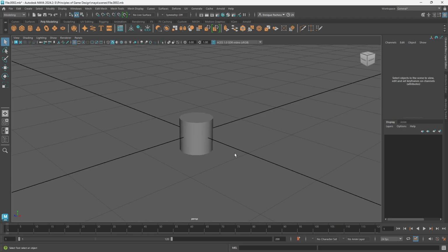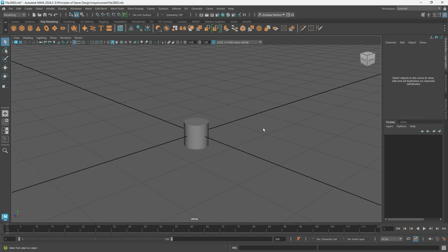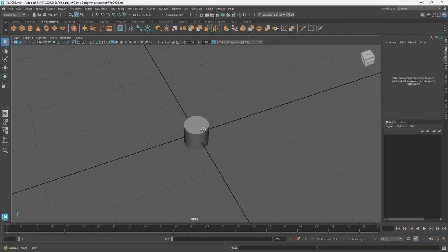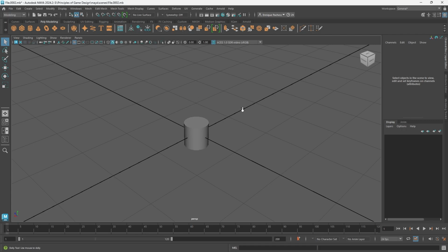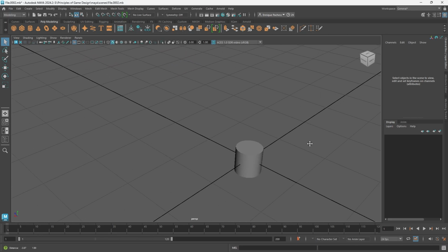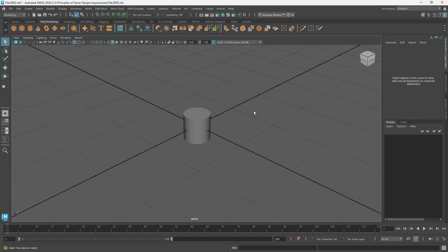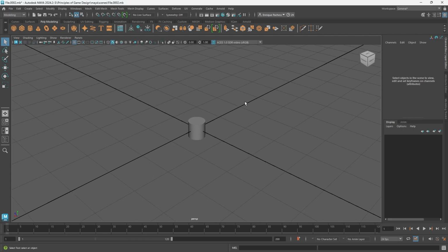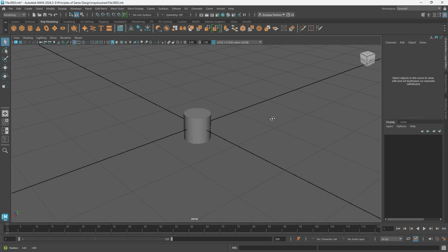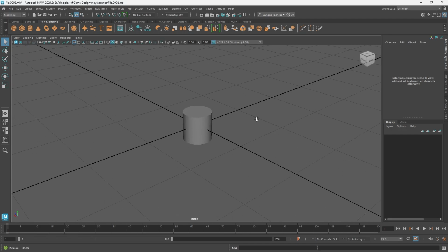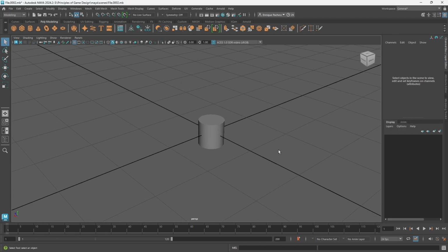So, to navigate the 3D space, you simply need to click in the middle of nowhere, hold Alt to rotate around an object, hold Alt and right-click to pan in and out, and hold Alt and middle-click to pan side to side. You can also use the mouse wheel to zoom. One more time: Alt left click, spin; Alt right click, zoom; Alt middle click, pan.